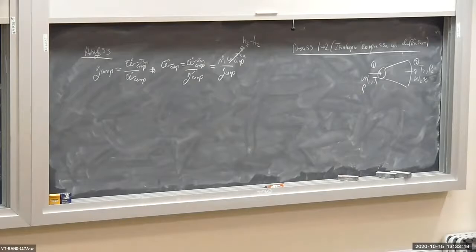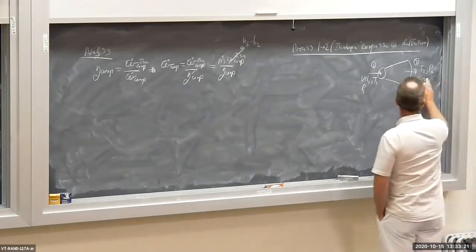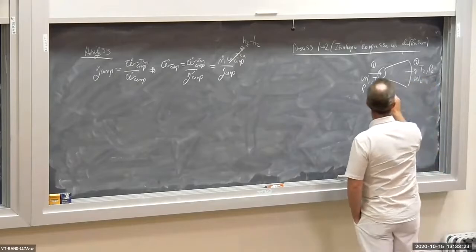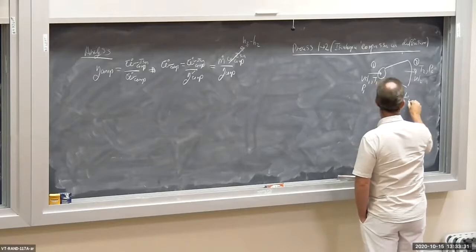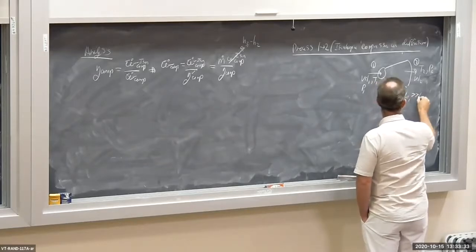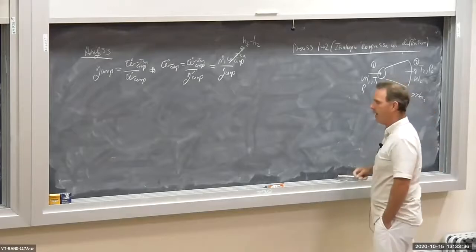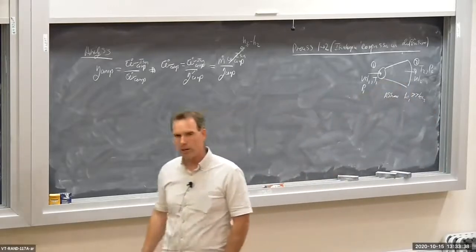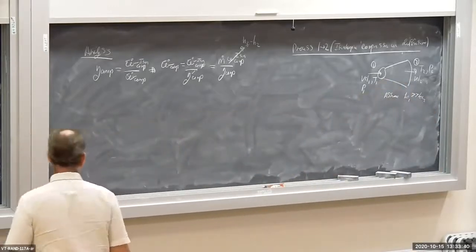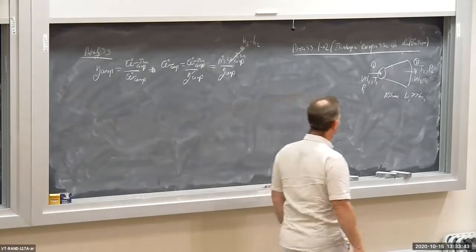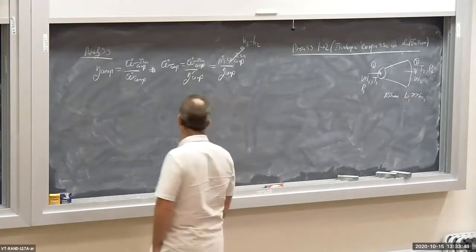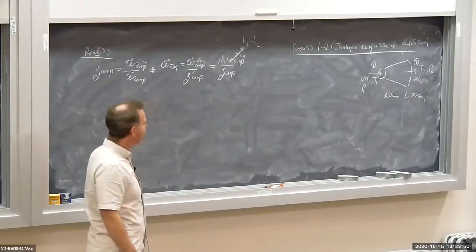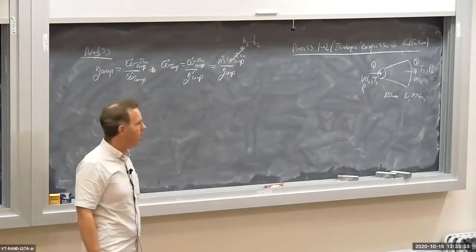For the diffuser, the kinetic energy at the inlet is much, much greater than the specific kinetic energy at the outlet. Essentially, the diffuser does its job and converts kinetic energy into enthalpy. So VEL2 is not really going to come up. I don't know what it is, so I'm going to neglect the kinetic energy at the outlet.